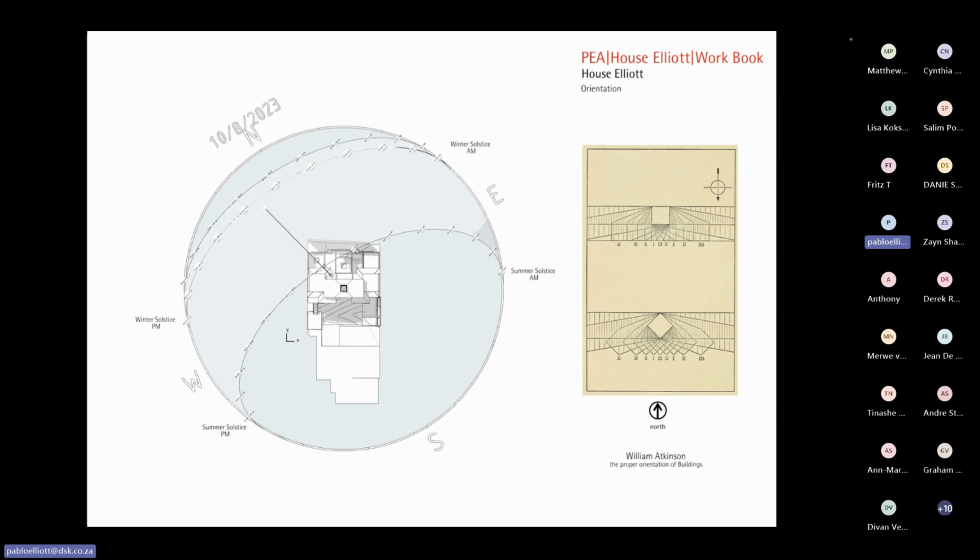So our square plan for the Mitchell's Plain Hospital allows sun to get to the wards at the back, whereas in that case, those wards wouldn't get it. So in Cape Town, we have this phenomenon where the city grid, which is square, actually faces north on the diagonal. So we are lucky that way, and hence even in Newlands suburbia, it's the same grid angle, and we're able to get the northeast aspect, which is very nice. The west sun we don't get so much, but that's mostly because of the mountain.